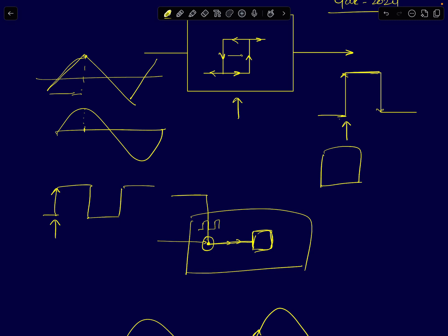Now usually these copper planes, depending on the frequency, if your frequency of the signal is very large, you can think of it like an RLC circuit. Which means it'll act like a low pass filter, and it will filter out all the harmonics. So what happens if you take a periodic square wave and remove all its higher harmonics? You are eliminating all the high frequency sinusoids, so what you will be left with is the fundamental sinusoid itself.